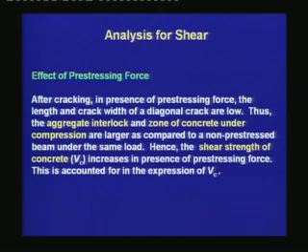The main advantage of prestressing is being reflected in this observation, that since the growth of cracks in a prestressed concrete beam is small, we have higher aggregate interlock in a prestressed concrete beam, we have a larger concrete in compression for a prestressed concrete beam.